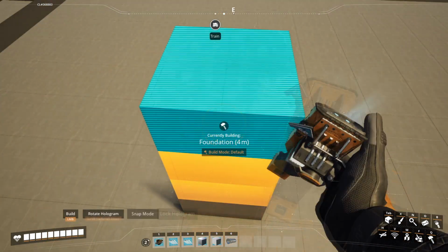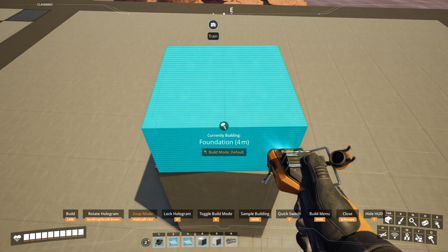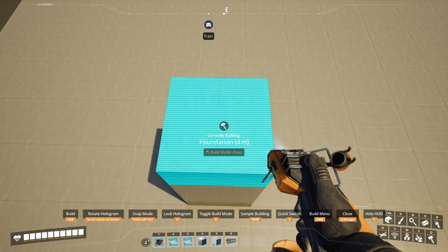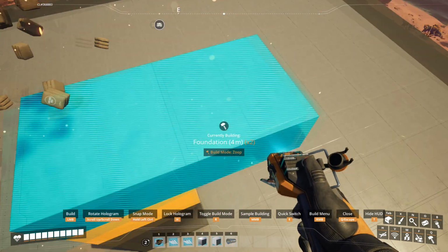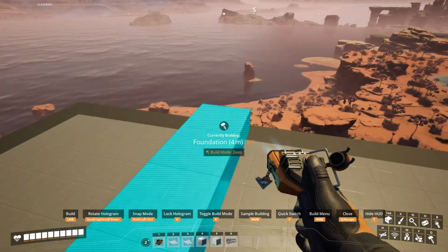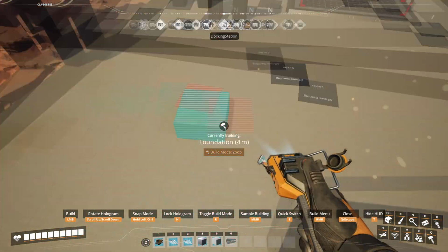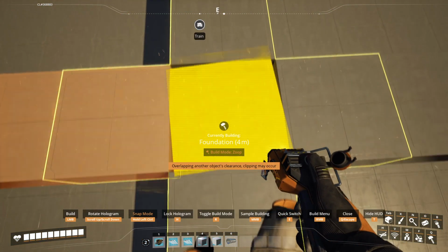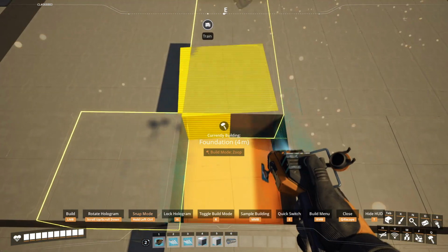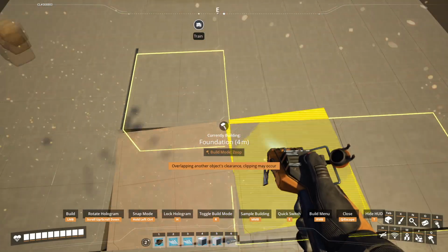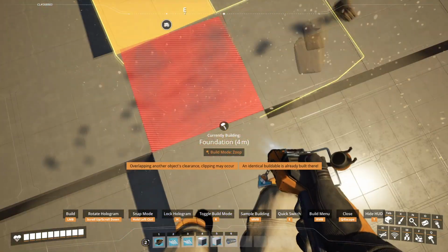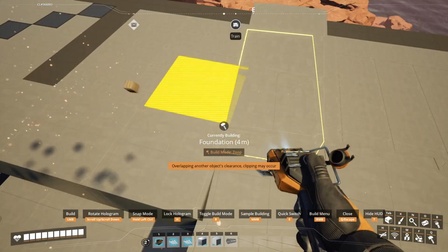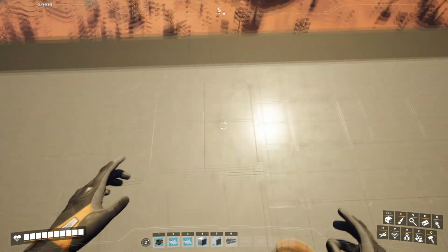And then if you want some simple horizontal circles, you can just grab a foundation and just press Control. Actually we'll start off with the square one, so we should just bring that out. This has been shown many times on YouTube, so I won't be too long doing this, but you just do that all the way out, delete the center one, press Control, that'll give you one degree, I think it's 10 degrees or 5 degrees it comes out, and you can just extend that all the way out to the edge, and you can see that's starting to create a circle.